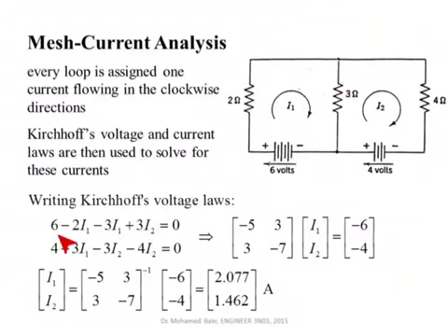So this will give us this first equation. This equation is nothing but Kirchhoff voltage law written for this first loop. And remember again that the current flowing in the 3 ohm is I1 from top to bottom and I2 from bottom to top. So you can actually say it is I1 minus I2 multiplying the 3 ohm. So we wrote Kirchhoff voltage law for the first one.